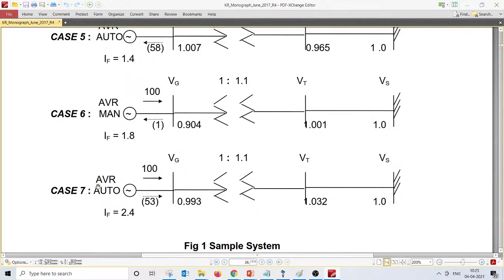That is especially needed in the present scenario where reactive power support can be an ancillary service, where you can make money from reactive power support alone, without also supplying real power, in the ancillary service market. So in order to extract the complete reactive power capability of the generator, the OLTC range which is selected is extremely important.